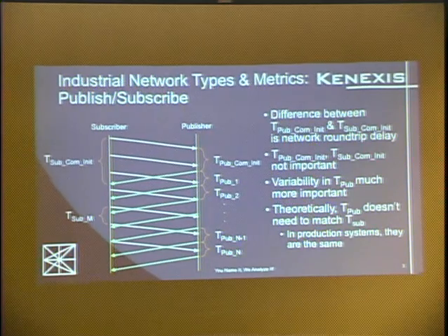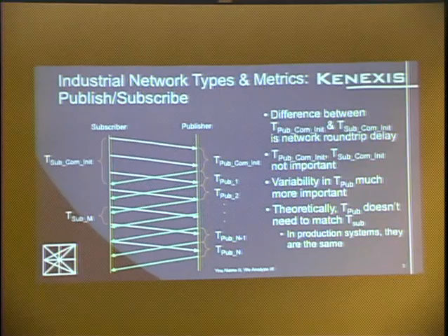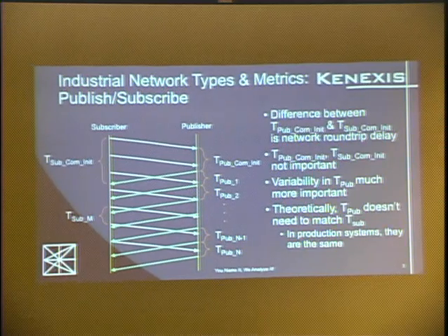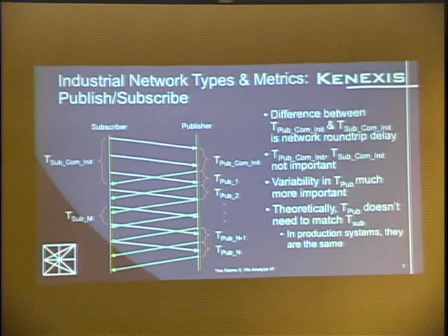And every 20 milliseconds or 10 milliseconds or 5 milliseconds, it'll just send a packet out. On the subscriber side, a lot of times there's a heartbeat, or if it's actually a two-way connection, there will be data coming down from the subscriber to the publisher. Maybe you've got a motor and you have to change the speed of the motor, so you actually have to send it different voltages, because the control loop is being done on the subscriber side. So the intelligence is being done on the subscriber side, being sent down.